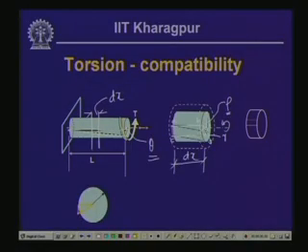So, this rotation we call d theta. Now, B moves to this particular point which we call B dashed. If we look from the cross section point of view, the radius is rho and the angle is d theta. So, BB dashed is equal to rho times d theta.